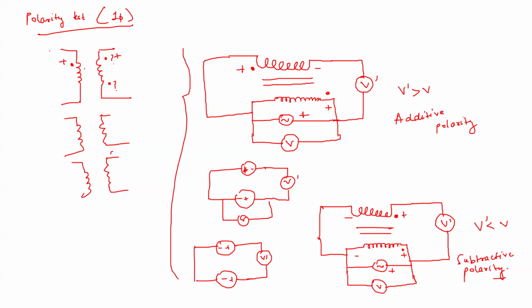If it is three phase, what happens? This is the three phase system. Here we have R primary, R secondary, Y primary, Y secondary, and B primary, B secondary. On each of the individual phases, you can connect them in series and apply this polarity test to get the dot locations in the three phase system also. Now we discuss the phasor groups.